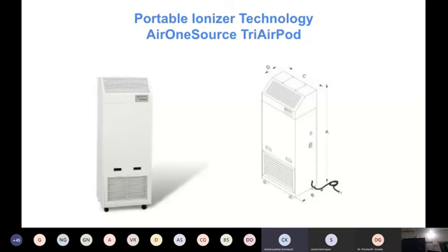We are using a ULPA filtration system. That means until 0.15 micron, it has got the filtration capability, that is down to 99.9997%. This equipment also uses the needle point bipolar ionization on the supply side. That means on the fresh air side, or on the return. Once the filtration happens on the recirculation side, the needle point bipolar ionizer is used. So the surface contaminants also will be eliminated to the majority of the extent in an existing ICU. The same can be utilized.